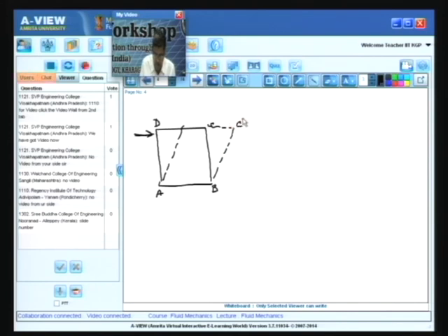It goes to a position A, B, C dash, D dash, where it has a finite deformation and resists the force under static equilibrium. And when this force F is withdrawn, then if the solid is a perfectly elastic solid or within the elastic limit, the solid relaxes to its preferred shape, the original shape A, B, C, D.